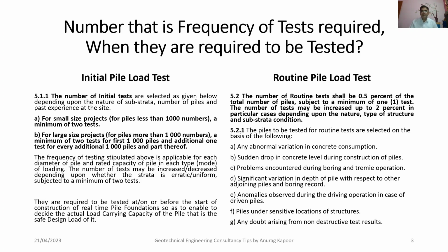Now, why is the initial pile load test required to be done? It is required to be done on or before the start of construction of the real-time pile foundations, so as to enable us, the civil engineering team, the contractor, the designer and everyone involved in the construction stage of the building, including geotechnical engineers and design engineers, to decide whether the actual load carrying capacity of the pile or the safe design load values are exactly as per our calculations or have gone haywire. So before starting our project we decide that the pile is safe for this load, and then we proceed with the piles so that our work is not interfered with in between.